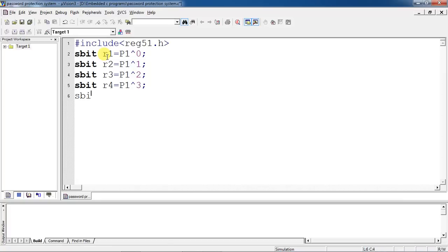And now I will go through the column connections. Column 1 is connected with P1.4, and column 2 is connected with the P1.5 IO pin, and column 3 is connected with P1.6. These are my hardware declarations. I'm doing it with a 4x3 keypad.